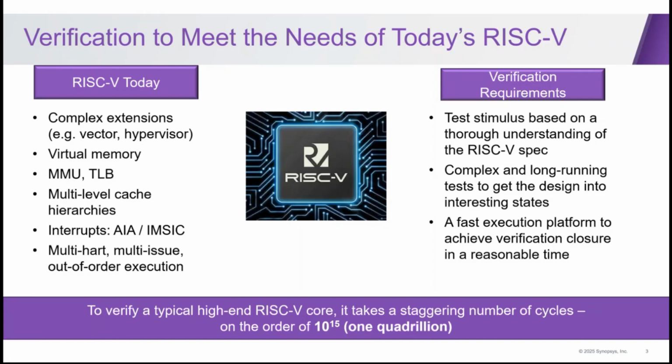Two years ago, in RISC-V Summit 2023, I think, the CEO of Imperas, if you're working on RISC-V design you may know this company is also bought by Synopsys now, Simon Davidmann, mentioned that you may need to run around 10 to the power of 15 cycles to get a high quality validation for your processor. So think about you need to run so many cycles to verify your processor.